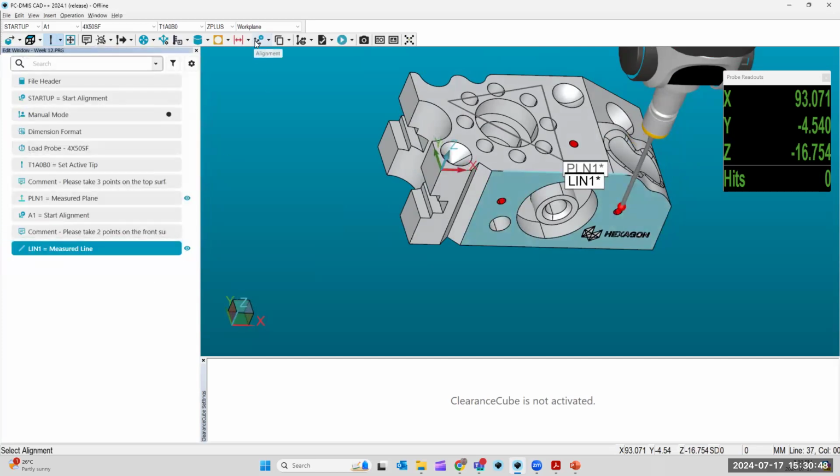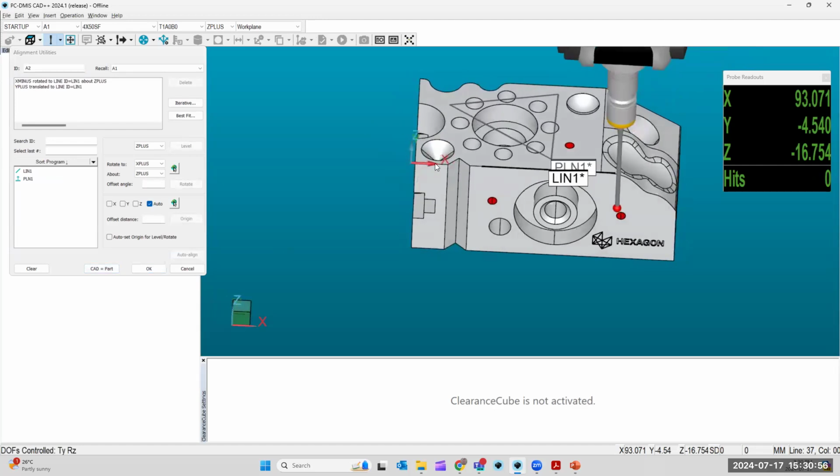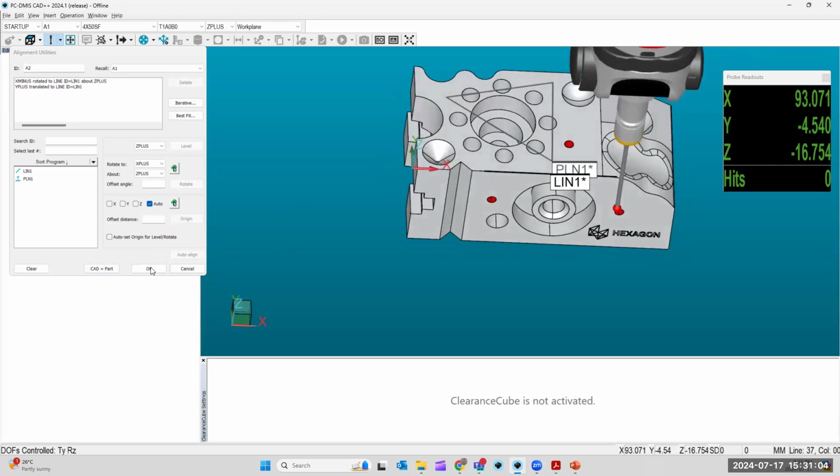And finally, so we've done our 3 degrees of freedom here. Our line is now something we align before we do our points. Now we do our line, auto align, watch your triad, and then you can see it's only open on the X, which means we don't have our 6 degrees of freedom yet. We've only got 5 constrained.